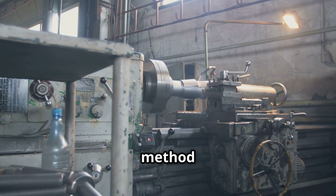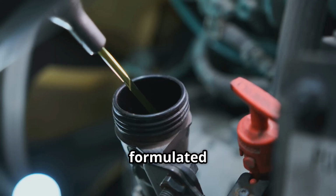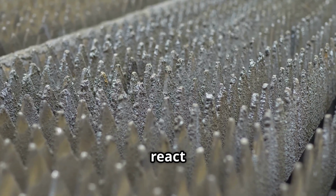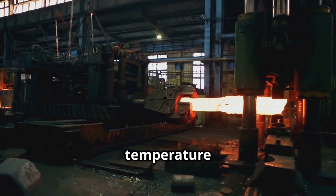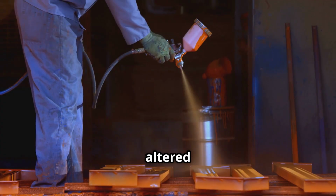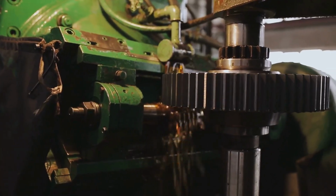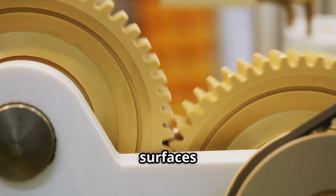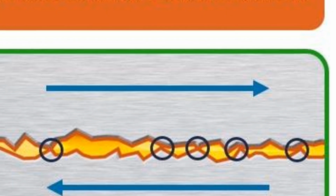A backup or secondary method of reducing this phenomenon of the boundary lubrication regime is with the use of a fully formulated lubricant that includes anti-wear or extreme pressure additives. These additives react with the metal asperities that have come into contact by responding to the high pressure and high temperature of contact and instantly forming an altered ductile or pliable film on the metal or iron surface. This new film then acts sacrificially as the surfaces slide or roll over each other. The chemical film formed by the additive is worn away instead of the metal surface.